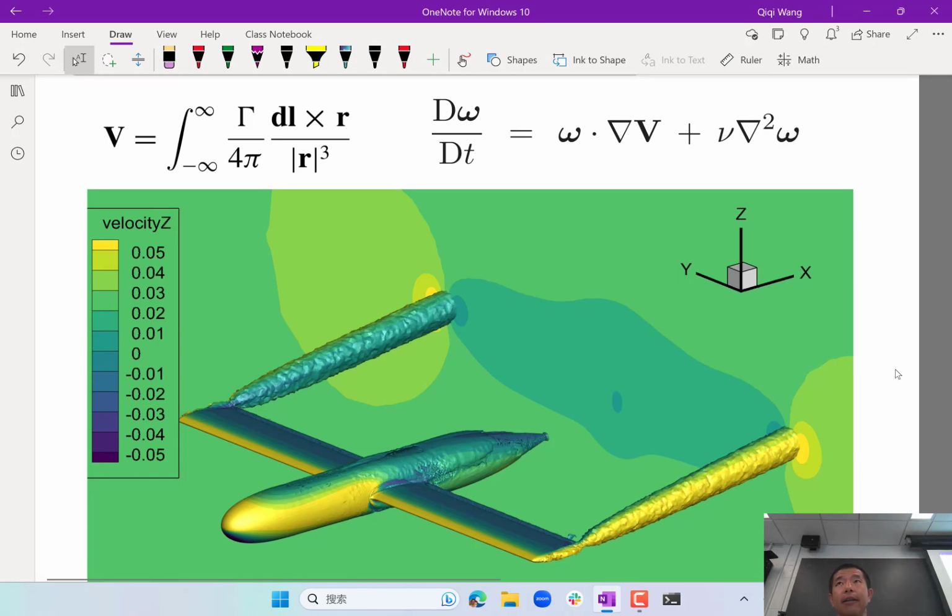And the symmetric component, or the average between one location of the matrix and the symmetric entry in the matrix, is called the shear. We're going to look at that later. That's what drives viscous stress. And basically, the Q criterion visualizes where vorticity is a lot stronger than the shear.